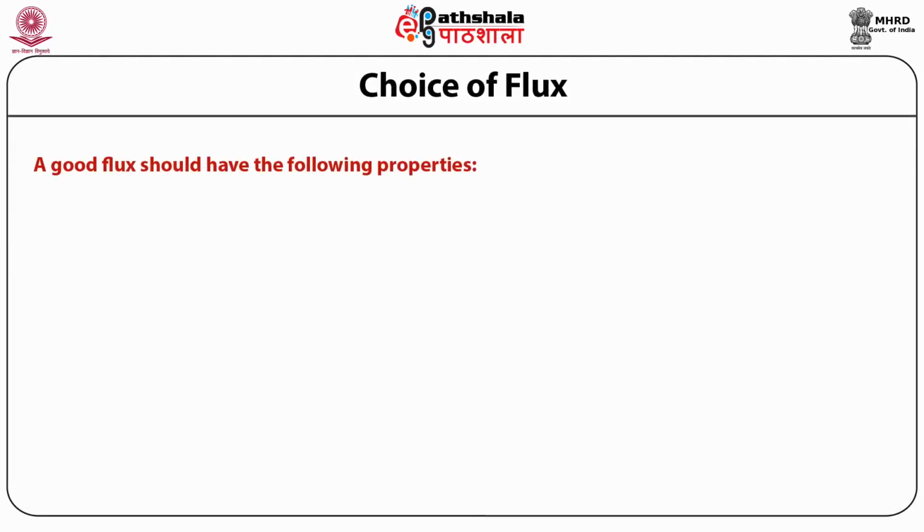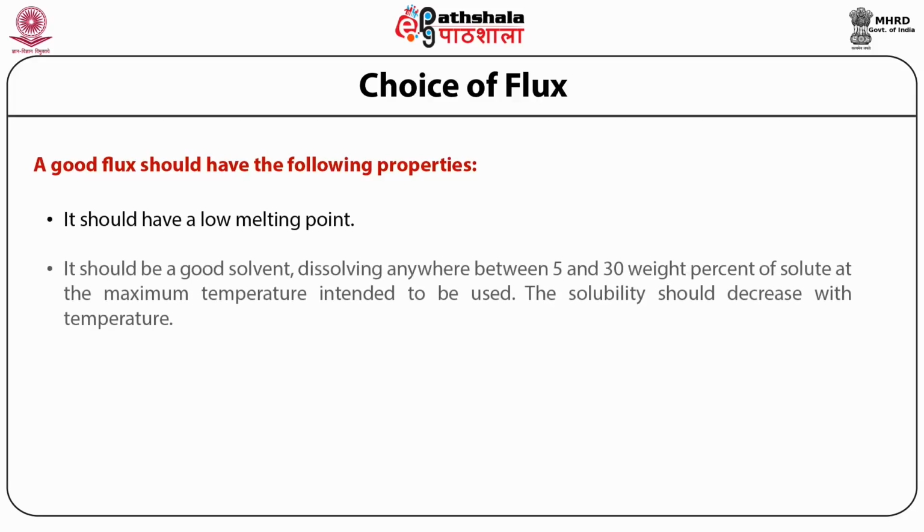A good flux should have the following properties. Number one, it should have a low melting point. Number two, it should be a good solvent, dissolving anywhere between 5 and 30 weight% of solute at the maximum temperature intended to be used. The solubility should decrease with temperature.